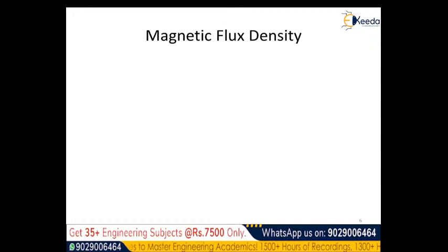Now very first of all, as we require capital H, the only parameter provided in this problem statement except the dimensions is the conductivity. We can use the conductivity with the help of the electric field intensity, and then we shall go for the magnetic field intensity. See here, for any material, if we apply a certain voltage at the two ends, and if we know the voltage applied and the dimension, then we can find the electric field intensity that exists in that particular material.